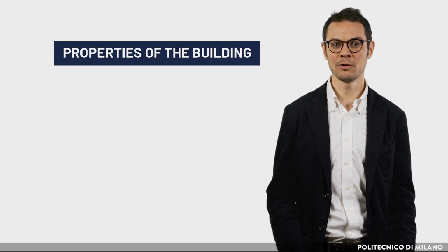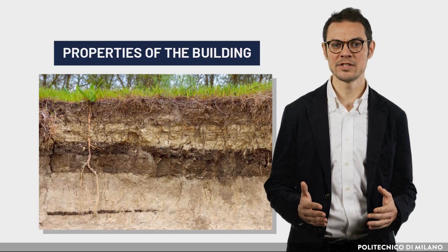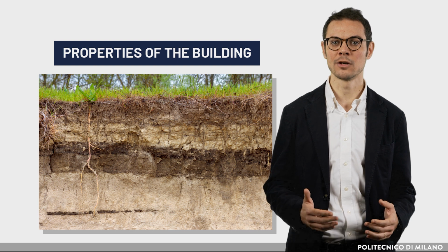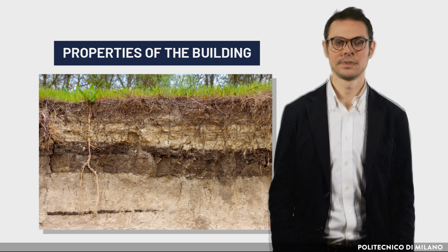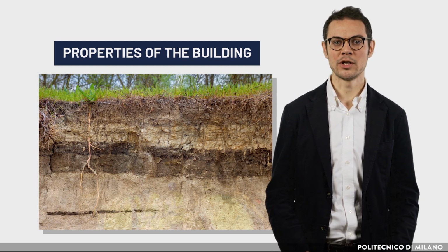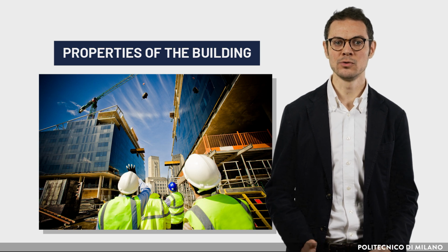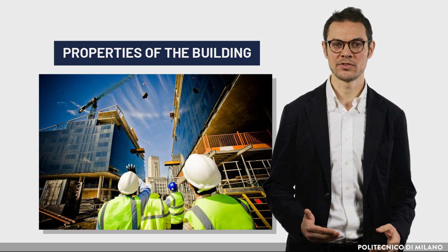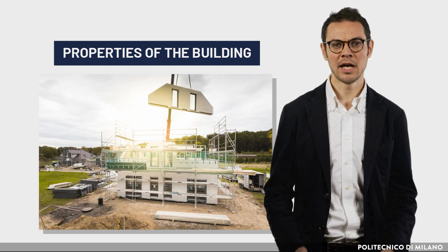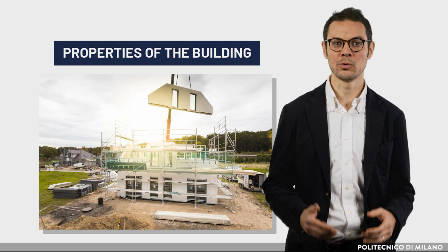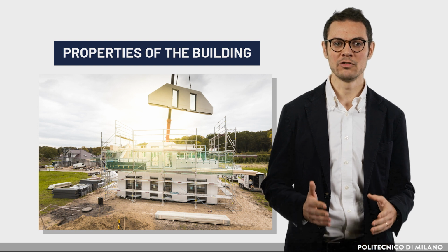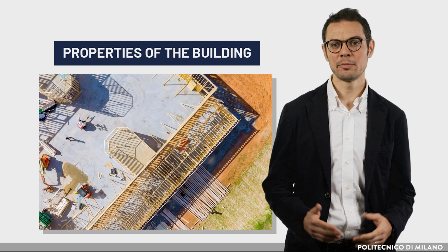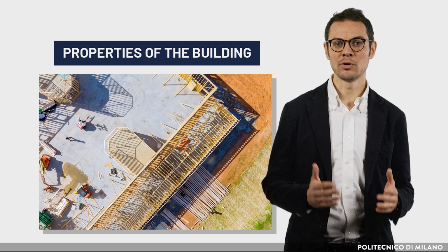Once the geometrical model is ready, the description of the properties of the building envelope, which include all the thermophysical features of the technological components, is required. In this regard, the knowledge of the technical and constructive solutions adopted, such as the thickness of the wall, the roof, ceiling, and floor typology, and all the elements which allow to describe the stratigraphy of the building's components, are pivotal to obtain reliable results.